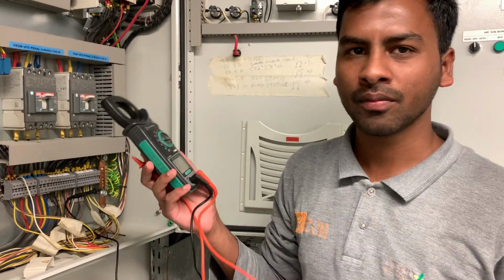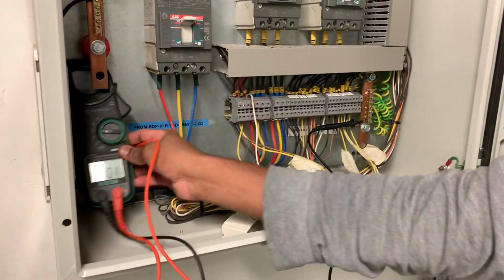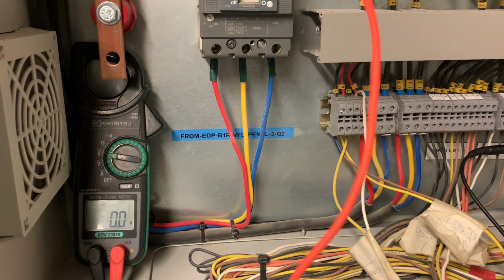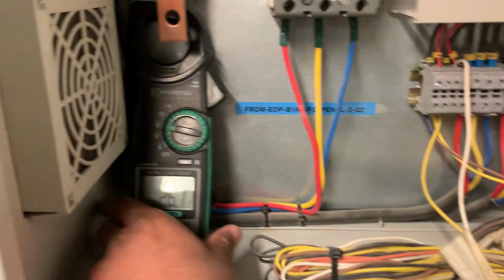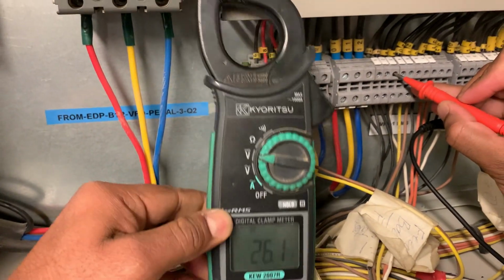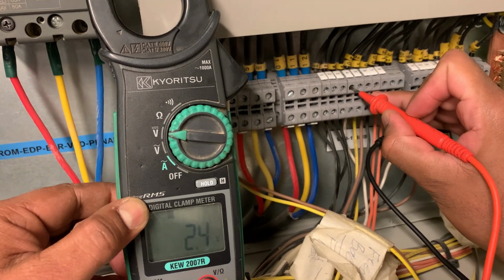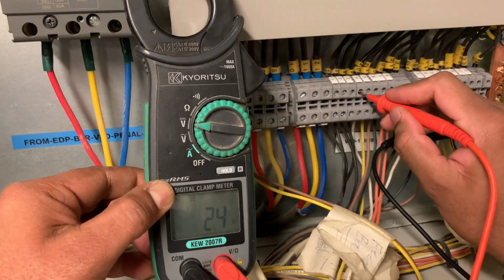I'll bring a clamp meter over here, and we will check the voltage. Let's check the voltage on the terminal 4 cable. As I told you, when there is a fire in the building, this terminal 4 is connected to pin 12. So let me check the voltage on 4. As you can see, it's showing 26 volts. And the other 4, this 4 connected to the VFD, doesn't have any voltage. As you can see, it's showing 2.4 volts, because a reverse voltage is there. So that's why the VFD is off.